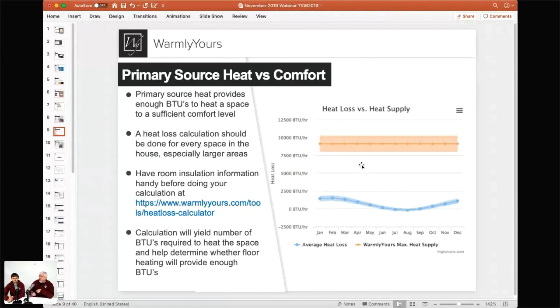But if no one's in there and you want to get that room warmed up, 100 degrees doesn't hurt anybody. So that's why we're talking about getting the room up to 100 degrees, possibly not the room, but the floor. But once again, that floor is not going to feel 100 degrees. That's the maximum that you can program the thermostat up to. What we're trying to get at is there's no restriction on the tile that there is on other flooring.